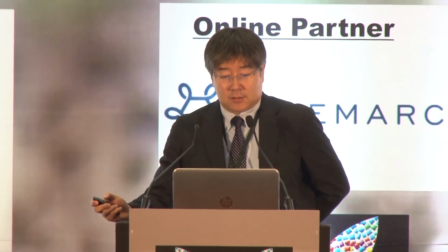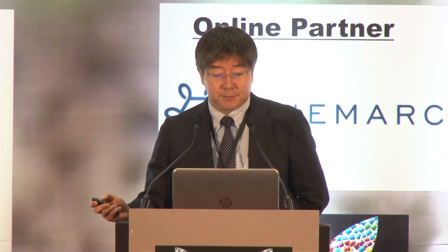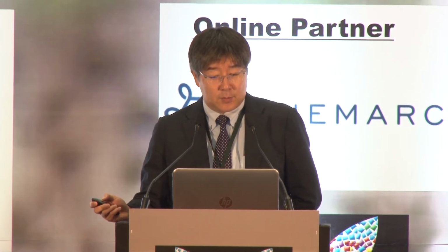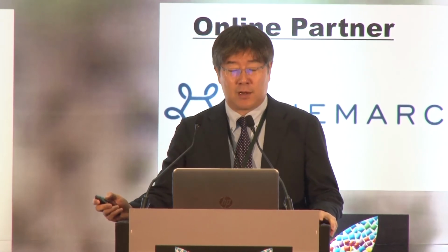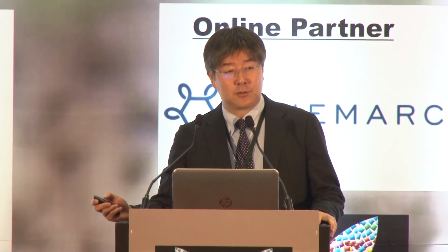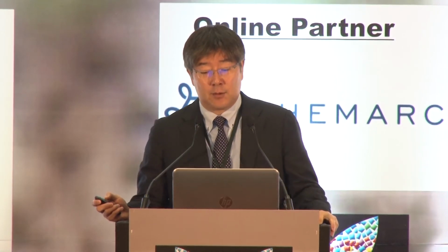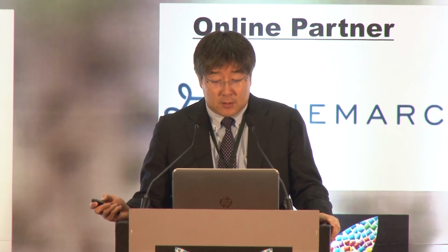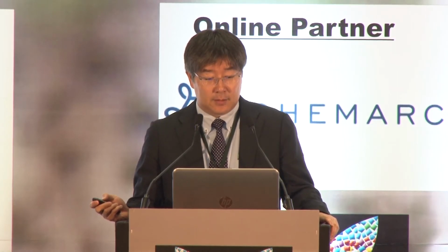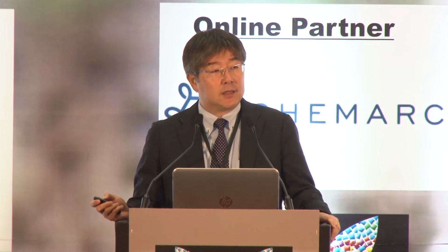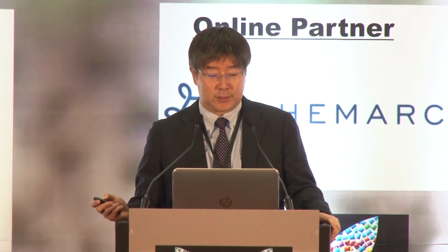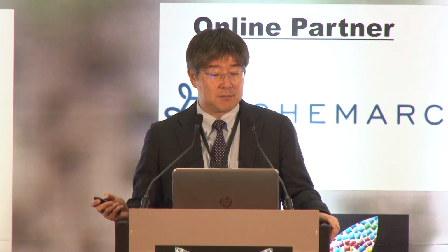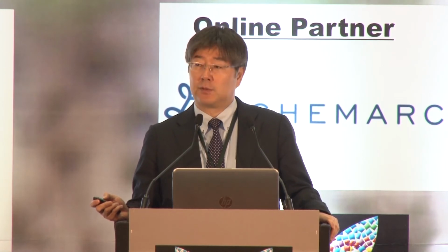This is anti-NOx discoloration behavior. AO1 is our AO60, equivalent to the 1010 type, and AO3 is our AO20, equivalent to the 1314 type. The condition of the NOx gas exposure is 700 ppm NOx gas at room temperature for 24 hours.